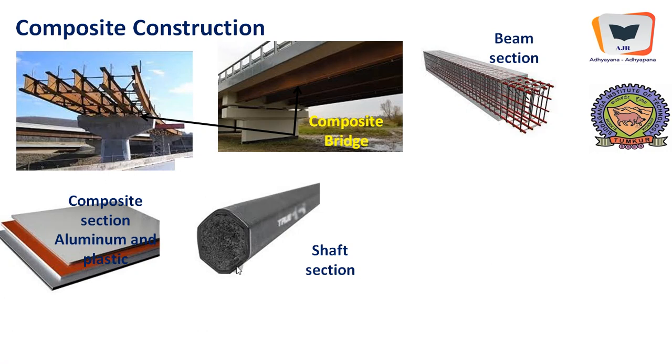And these shafts are subjected to torsion, and torsion we will see later in our continued tutorials in the unit where we discuss the shafts and shaft action and the torsional shear, etc. We will see the shear becoming very critical at the periphery of the component, and at the periphery we have placed here in this particular example a strong steel or hardened steel which will take enormous amount of shear.